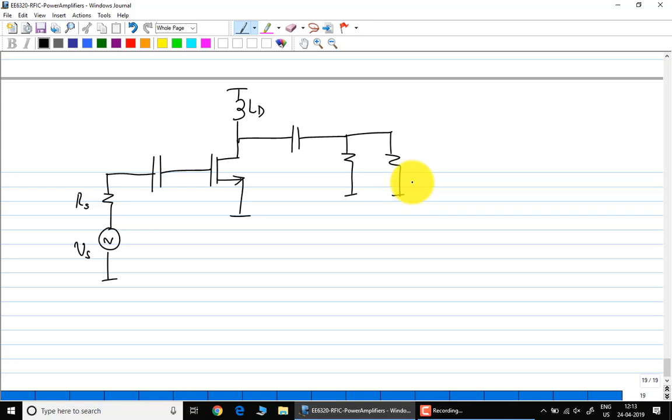So this is the circuit that we have seen. This is RL prime. Now he is asking, why not put an output matching network? Let us say you do this. If instead of 50 ohms you had matched down to 10 ohms, you will need an RL prime that corresponds to 10 ohms output impedance. First of all, this RL represents whatever is matched down from 50 ohms if necessary. Now what he is suggesting is, why not match down to the real part? Is that what you are asking?